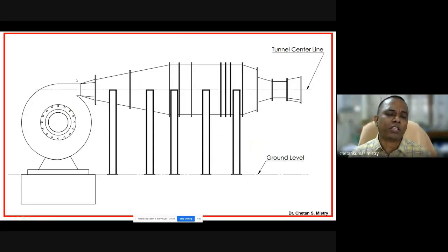Based on our expected Mach number of 0.64 at the exit of my nozzle, we have done our calculation of what mass flow rate is required and what pressure rise we are looking for from the blower. Now based on those blower dimensions, if I accommodate my sector annular cascade tunnel, that's what is showing me here.